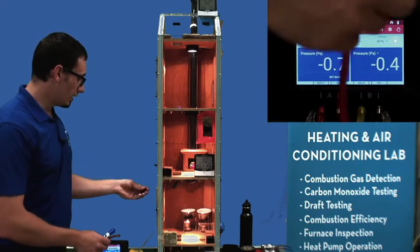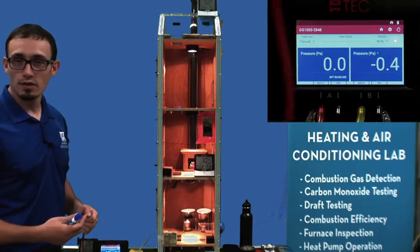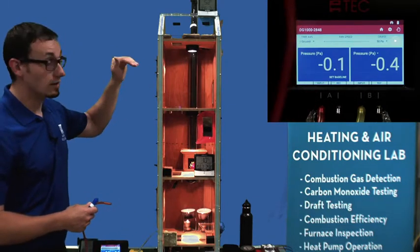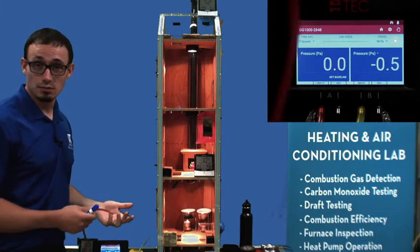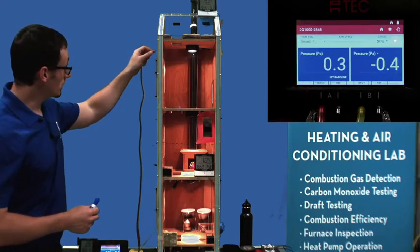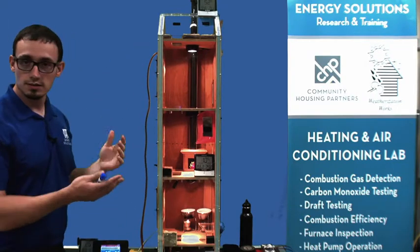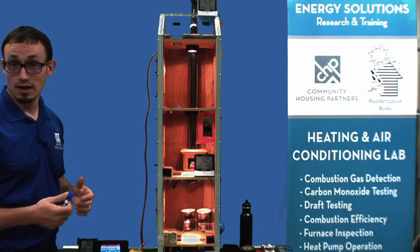So I've got a pretty even amount of pressure, high and low, but really all that that's telling me is that the size of my hole from the house to the attic, and from the crawl space to the house, is the same size. It's really all that that's going to tell me. So I'm going to plug this back in, and I'm going to manipulate my hole sizes, top and bottom, and we're going to see what happens as a result.